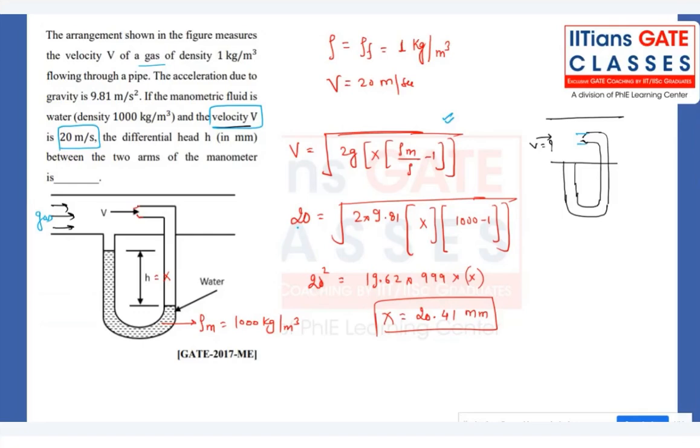You only said that fluid has to be brought to rest condition, right? Isentropically. Definitely, then only we can measure the stagnation pressure. Otherwise it is impossible to measure the stagnation pressure. We cannot measure stagnation pressure unless we have this mouth opening, just like a narrow one, where the fluid is brought to the rest condition like this. It is a very small opening, almost no opening. So velocity will be zero at that point, right? Now, make a note of it. Once it is done, let me know.